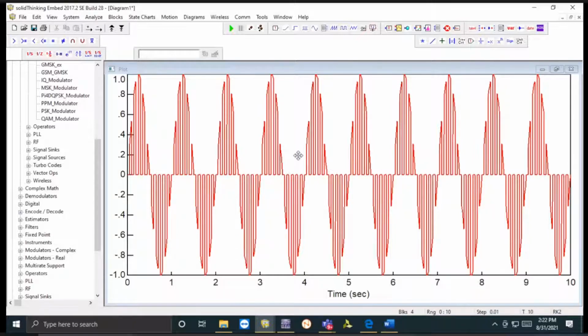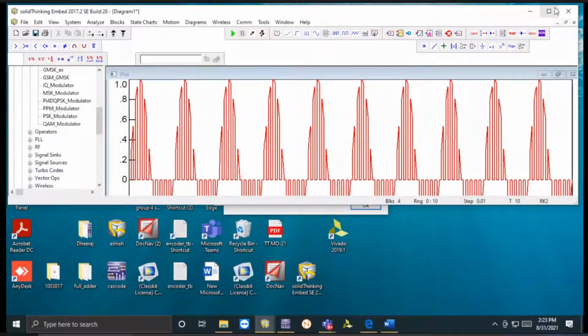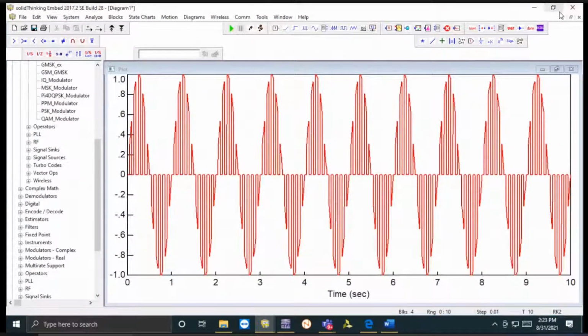Actually, we are talking about the integrator where we have the resistor and the capacitor, so that will charge up to the peak point and then discharge and again charge up to the peak point. Likewise, it connects all the peak points of this input signal. So this is basically an integrator, which is a low pass filter. Low pass filter is nothing but the integrator. So we are going to use the low pass filter here, the integrator, to reconstruct the signal back.